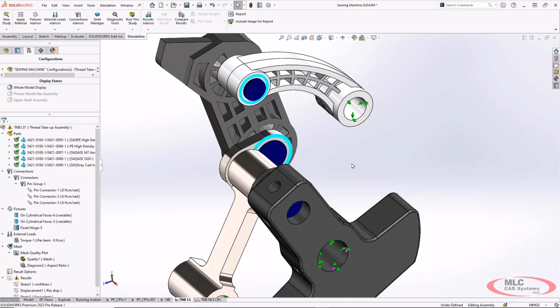So this is a tool that I'll now recommend everyone run when they're analyzing assemblies, because it's a very quick way to verify your setups. So, a great tool to be able to use. And again, to get there, just go to Diagnostic Tools, Underconstrained Bodies, and you can launch that command for it to run.